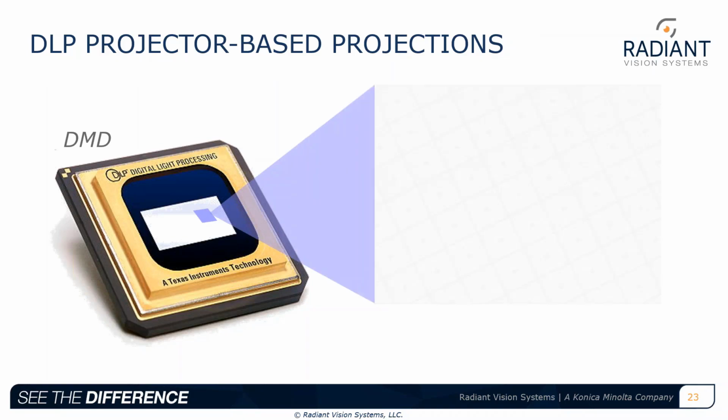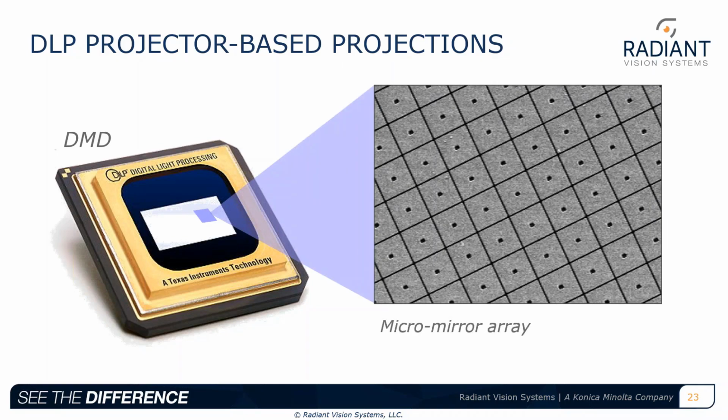DLP projection technologies for head-up displays rely on a digital micromirror display, or DMD, an optical microelectromechanical system that enables spatial light modulation. Each DMD contains up to 8 million individually controlled micromirrors built on top of an associated CMOS memory cell. Improper mapping of the image with the DMD mirror array can cause modulation between contrasting areas of the image. This manifests as spatial frequency noise or blurriness that we might see in the projection as the contrasting areas get closer, reducing visible resolution and contrast.